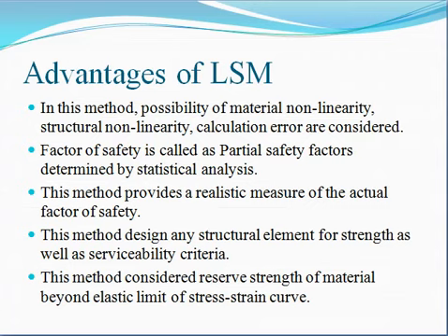Factor of safety is called partial safety factors, which are determined by statistical analysis. Means here we use the partial safety factors, which account for material non-linearity, structural non-linearity, and also for the calculation error.